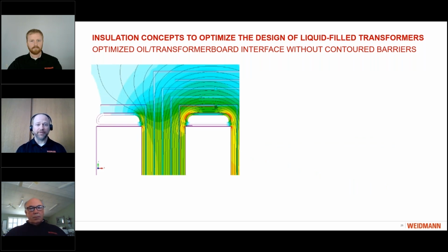All right, the simple imagery here, what we're looking at is the same 2 coils with some barriers between and some 90-degree segments. Previously, we'd only been showing broken down ducts with barriers between the coils. Now we've added insulation barriers at the tops of the coils. That would go from the top of the coil up to the core yoke. In this case here, it's a 90-degree segment. You can see a thin red line with the letter B telling us where it terminates. The letter A, where it begins, would be well below the bottom of the screen there.